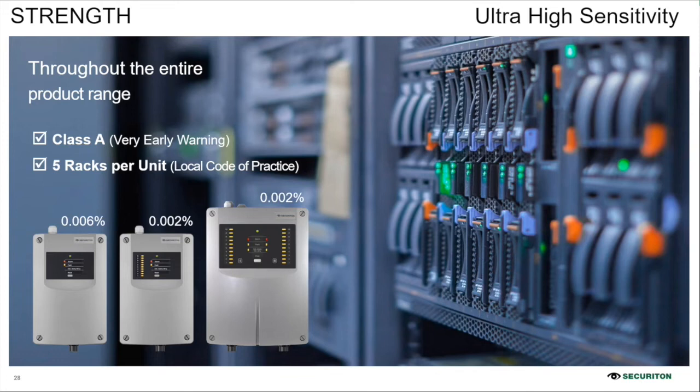And as per NFPA, a system that detects low energy fires before the fire conditions threaten mission critical application services, with the benefits of staged responses with the sampling hole sensitivity. The alert is around 0.66% obscuration per meter. It is 0.2% obscuration per feet I'm talking about.